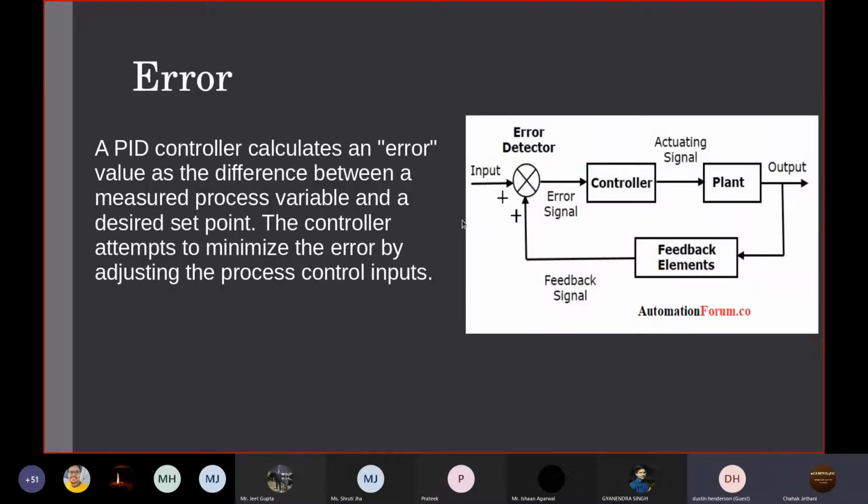Now, what do I mean by control loop mechanism? Here you can see, I hope everyone can see my mouse pointer. We get an output from the PID controller, and we get an error. The error is the output of the feedback control. We want something to stay at a certain value, that is the desired set point, and we have the current value of the controller. Now error is the difference of the current value and the desired set point.